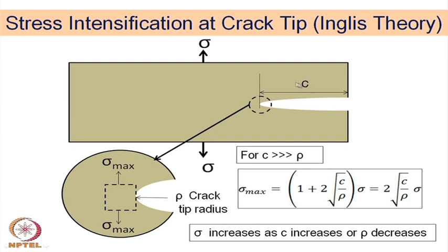So, the flatter region will have more or less the same stress, but the stress will be maximized at the crack tip, which is more critical, because this crack is trying to grow in this direction, and the higher the stress here, obviously the extension or the propagation of the crack will be faster, will be easier.